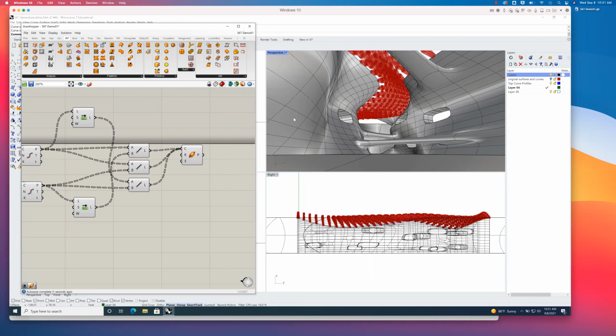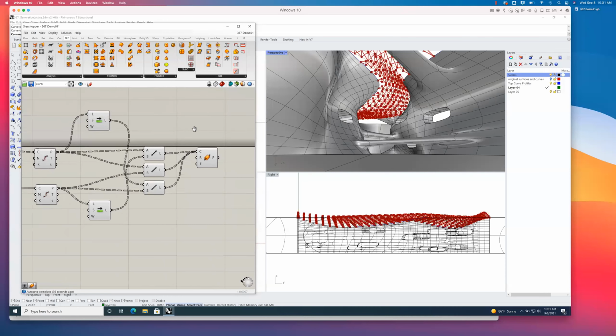That radius seems ridiculously large. Those are way too beefy. 1 foot diameter, or is that radius? 1 foot radius seems a bit extreme for little truss members. Since I'm modeling here in feet, and you'll see that your units are set to feet in the file I give you, if I thought about this, let's say the radius is 2 inches. So 1/6 of a foot, I'll just go with 0.15 feet, somewhere there. There we go. That's better. Oh yeah, that's so much better.